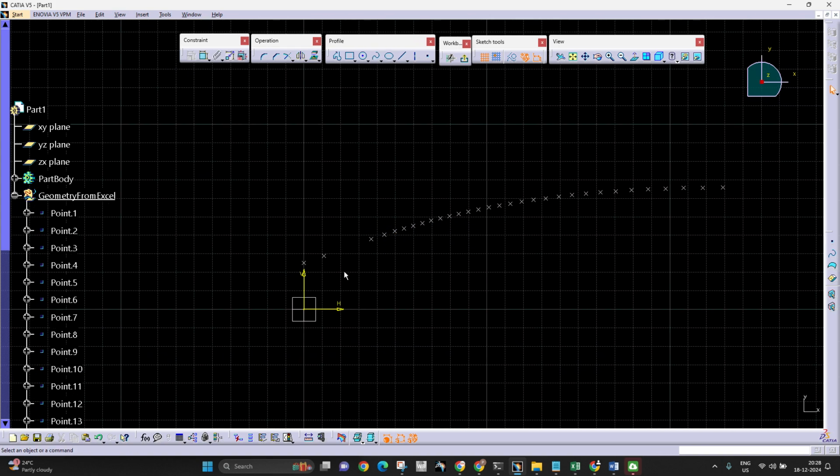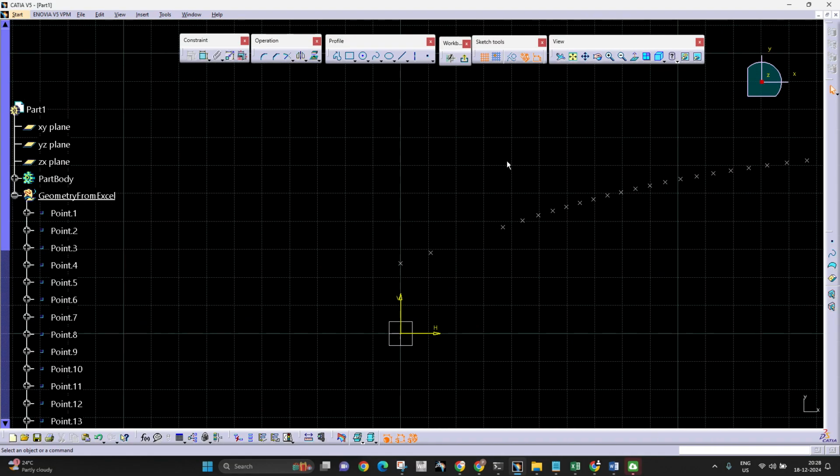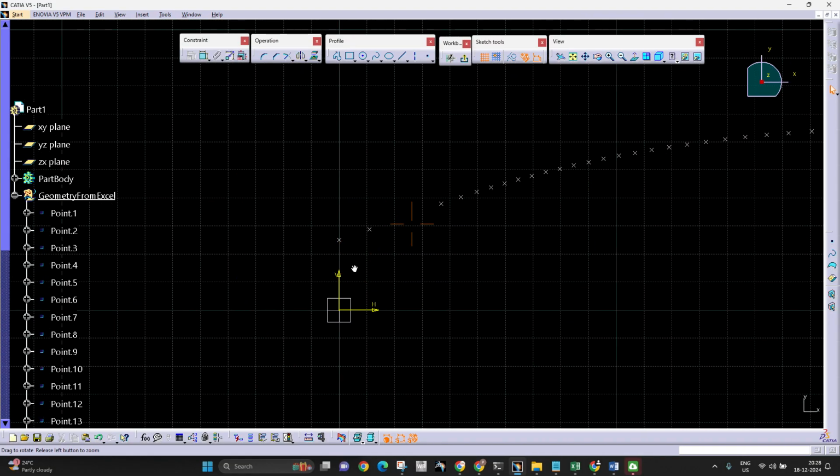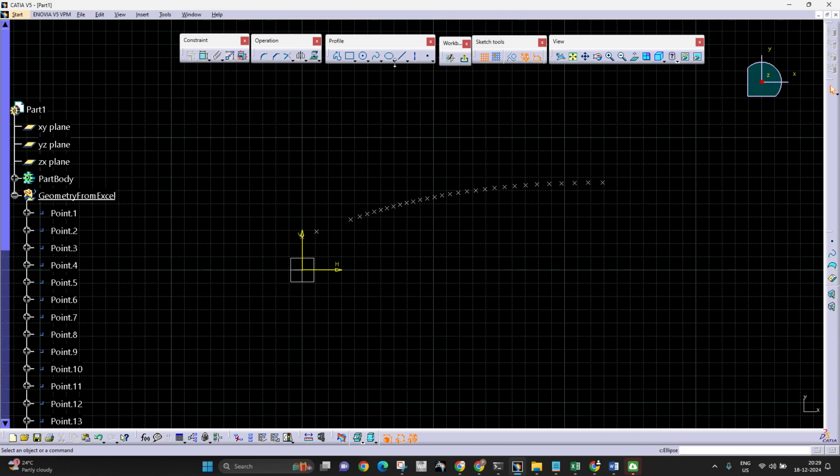The reason why you only got the outer curvature is because MOC focuses only on the pressure dissipation and the velocity increment. When it comes to the convergent area, that can be done freehand, literally freehand. You can make a straight line, curvy line, or a rectangle, literally anything. All you need to do is make sure the throat has exact Mach 1. If you maintain that, you're good to go. I'll show you right now.